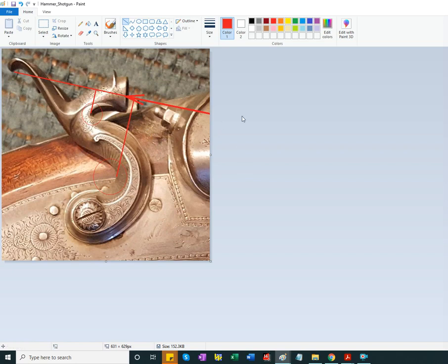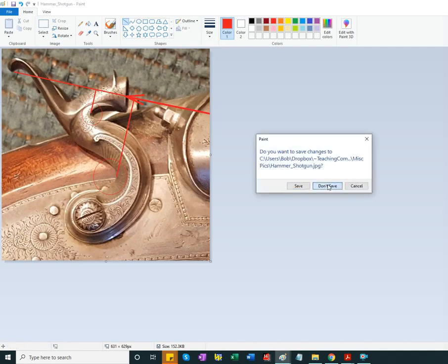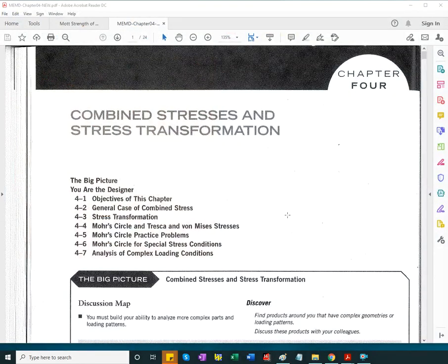Yet another application example of curved beams and how they have been implemented in practice. So again, to account for a bigger bending stress, the radius of curvature is bigger than it is here. For the same force, the arm is less here and it's bigger here, causing a bigger bending moment. Quick reference to the previous chapter, the section on curved beams.